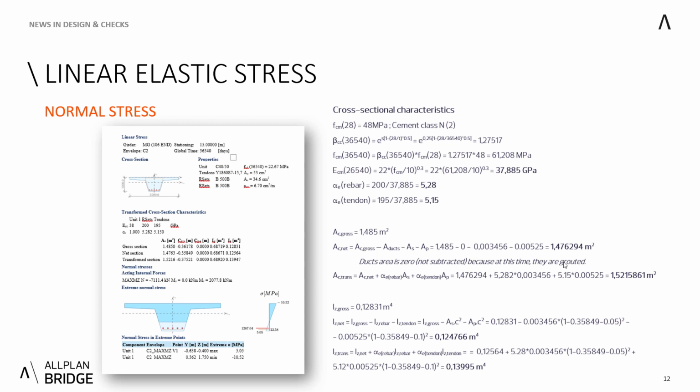And therefore, we can recalculate the Young elasticity modulus, or this mean modulus, to 37.9 gigapascals, which is not the value that is applied at 28 days. And when we have this value, also you can see it in the report snippet, there is this rounded value to 38 gigapascals. We can recalculate the rebar and the pre-stressing steel by this working coefficient alpha E to the concrete. So we consider 200 gigapascals for the mild rebar and 195 gigapascals for the pre-stressing steel.